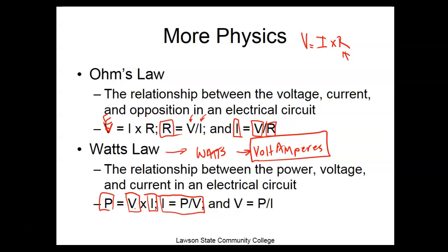But the problem we have is that once I've set a wire, then I would determine how much, your power company calls it line loss. How much push do you lose in your lines, in your conductors? Well, what they found out a long time ago is that the amount of voltage drop we get is the current times the resistance.